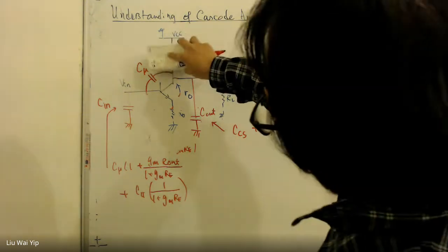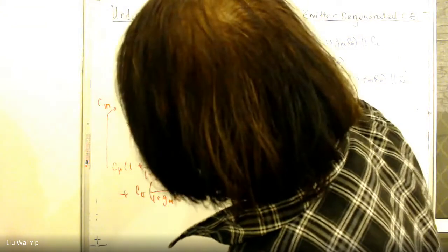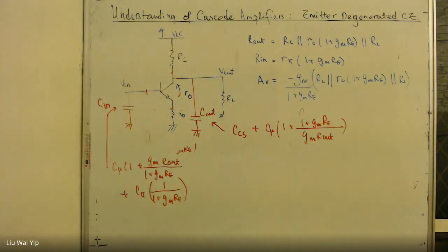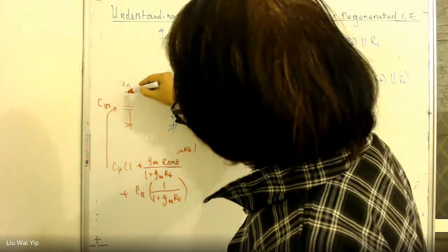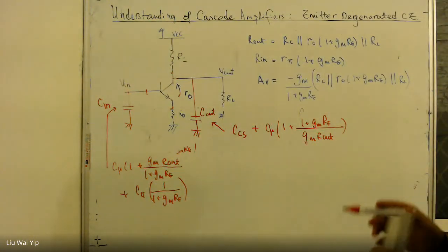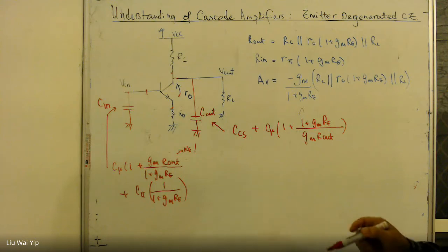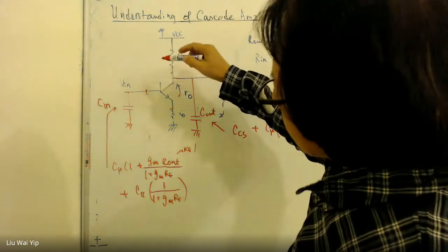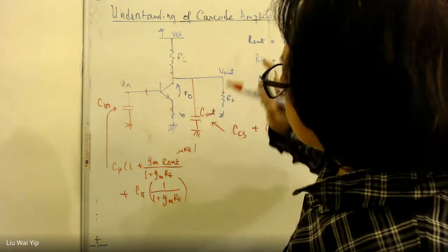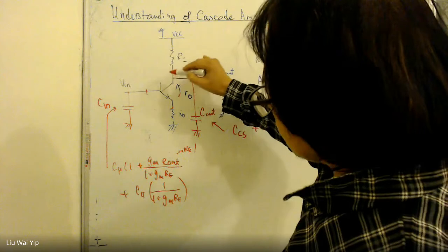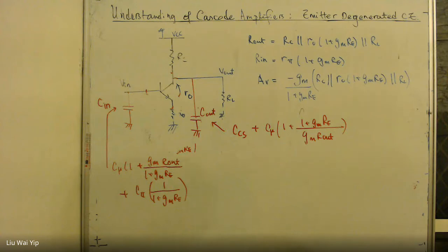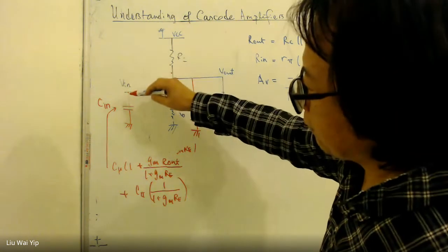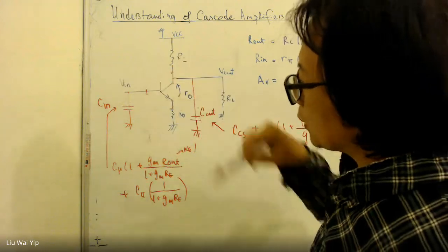Now this capacitor has been transformed, so it should be erased. The poles can be directly determined. Under the Miller effect, every node in the circuit can potentially produce a pole, depending on the equivalent resistance and capacitance pathway connected to the ground.